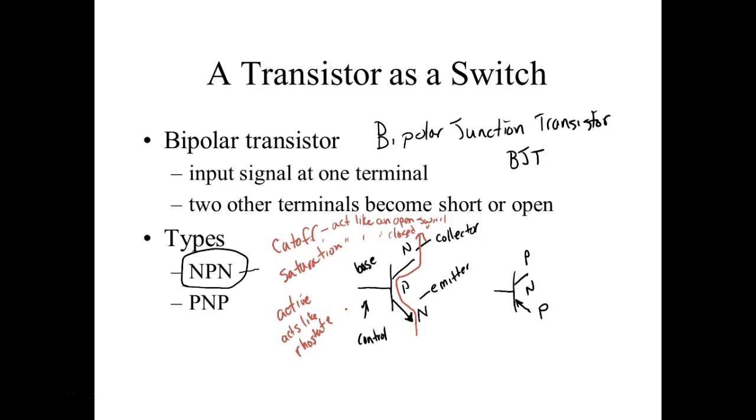So what that means is, if I put a 0 over here, then this is going to turn off. No current flows through it. If I come over here and put a 1 over here, we're going to have to put a resistor, guys. We'll talk about that later. Then that 1 is going to provide enough current to saturate this thing, and the maximum current's going to flow. The only thing that's going to control that current is what load you hook this thing up to. It's got to be hooked up to some type of load, right? You understand?